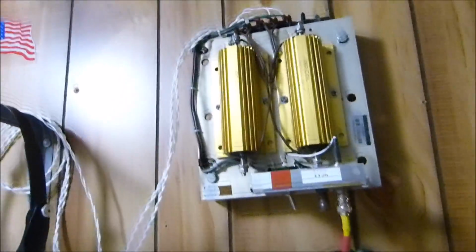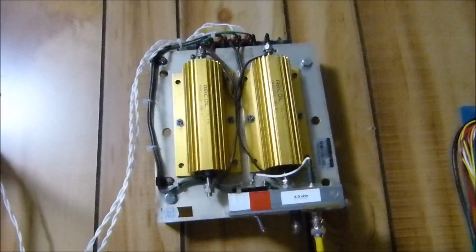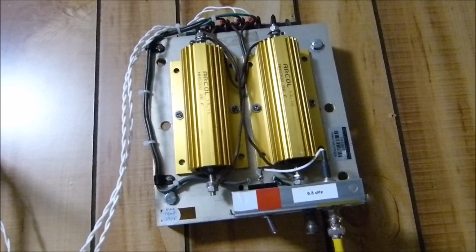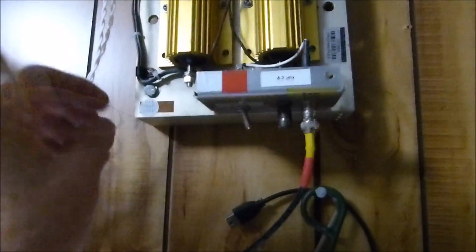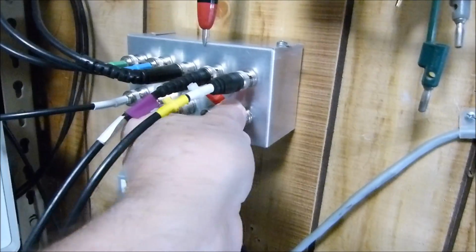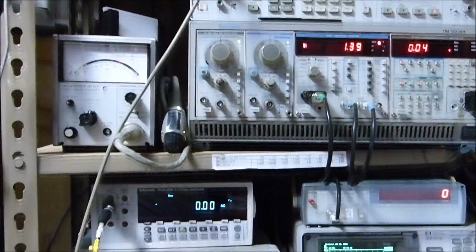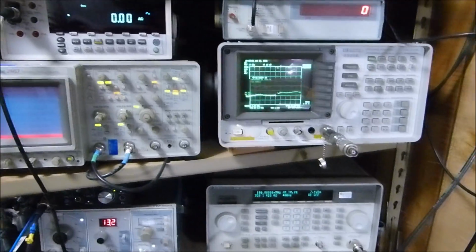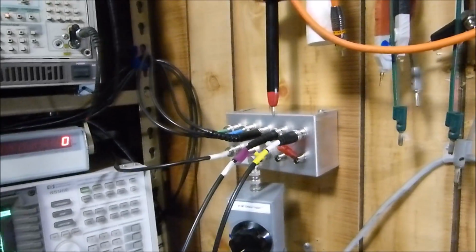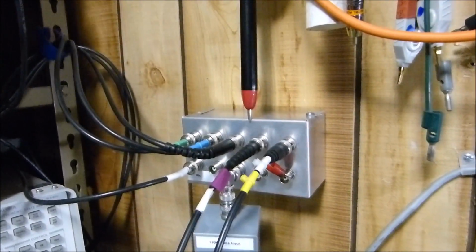This is part of the audio measuring devices. These are two big 300 watt 1% non-inductive resistors. These are the wires that go out to the left and to the right channels. Now switch left and right here. This left and right switches this wire right here, which feeds this box right here. Actually, it's hooked up at the moment. It's this wire right here. I take it off if I'm not using it. If I want to feed this breakout box, which feeds all the equipment at once, so I can look at all these parameters at one time without having to go from one to the other. In the audio range, it's not going to work very well in the RF range.